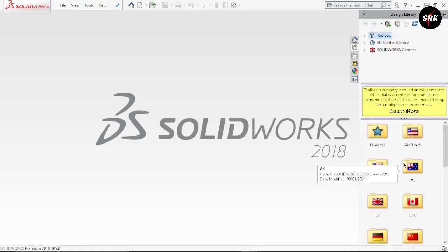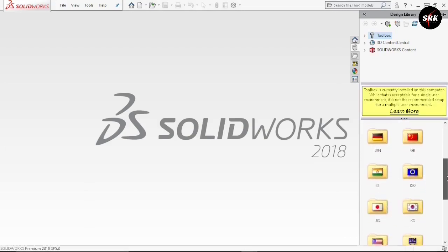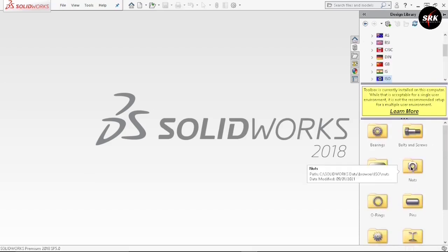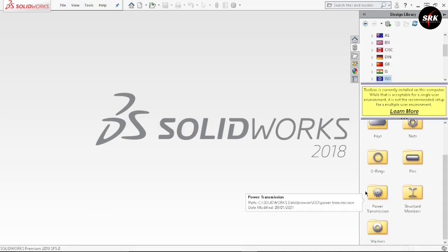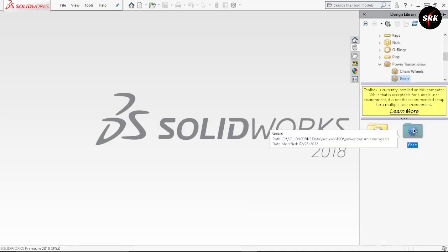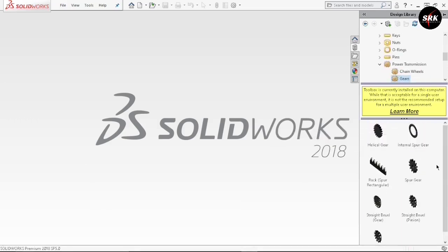And after a few minutes, you will get this kind of folders. Just scroll down and search for ISO. Just double click on this ISO. Now we are supposed to design the gears. So search for this power transmission. Select on this gears. Now you will get different kinds of gears. Among these, select this spur gear. Right click on it. Select create a part.